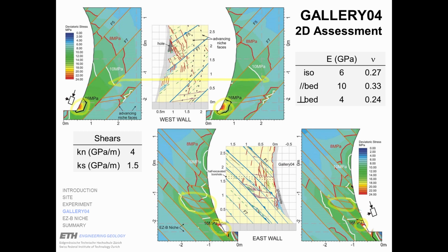So these reactivated tectonic shears have a strong impact, maybe not only on the stresses that evolve around the tunnel, but also on the induced fracturing, because most of these fractures that are shown here in red, in fact, can only form because of slip along the bedding parallel and also non-bedding parallel shear zones. So matrix anisotropy plays a lesser important role than these tectonic structures.